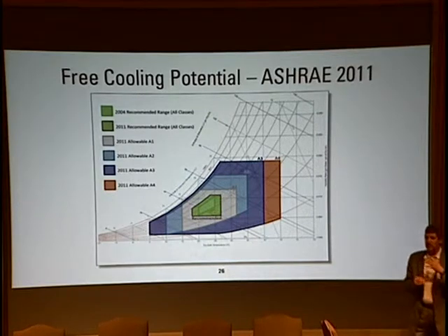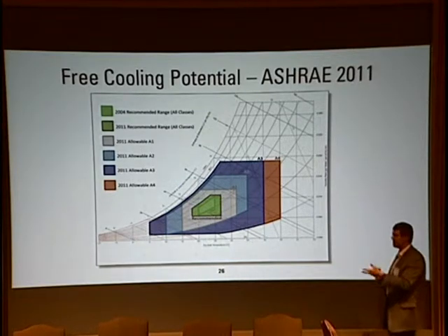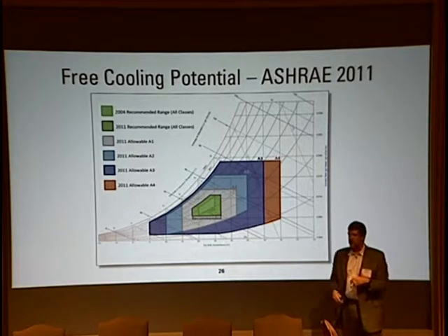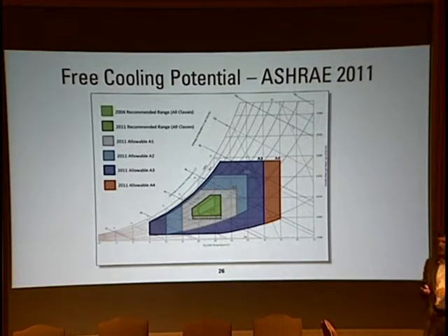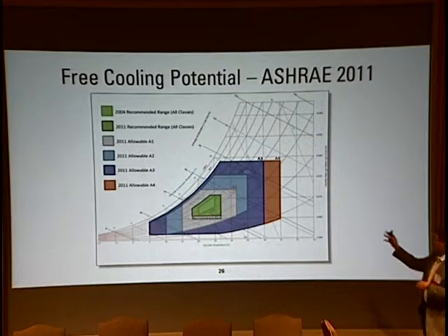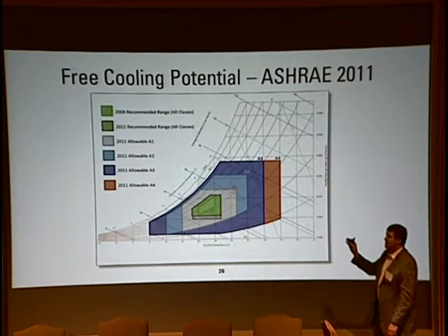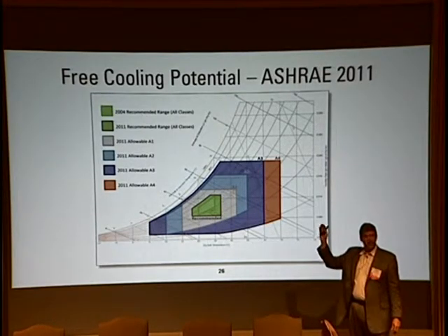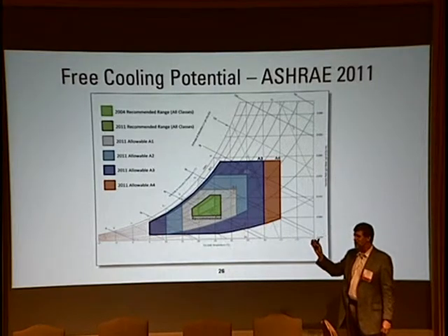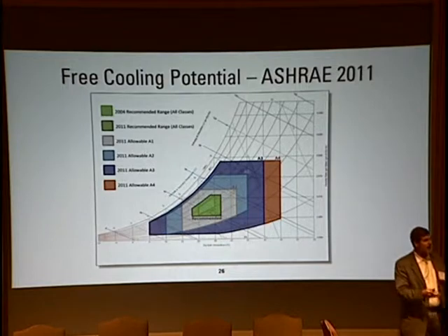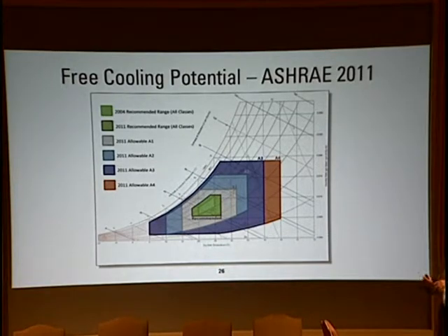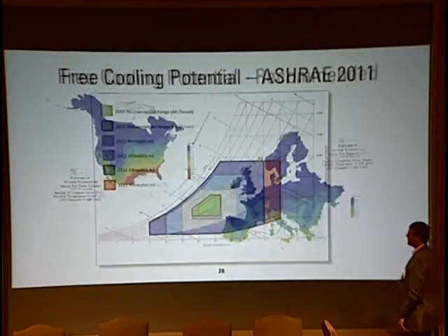I also wrote a paper that looks into that a little bit more. This chart is actually from the Integrated Design Group paper that was published on the impact of ASHRAE on reliability, because that's one of the biggest reasons that we condition the space at all: reliability of the IT equipment. And I could go to any IT guy and argue, if you run it hotter, yes, you'll lose a few hours, but I can almost guarantee you won't be able to see it in your measurements. And if you run it a little bit cooler, you'll get more reliable, and I can almost guarantee you won't be able to see that either. So the net effect should be nothing.